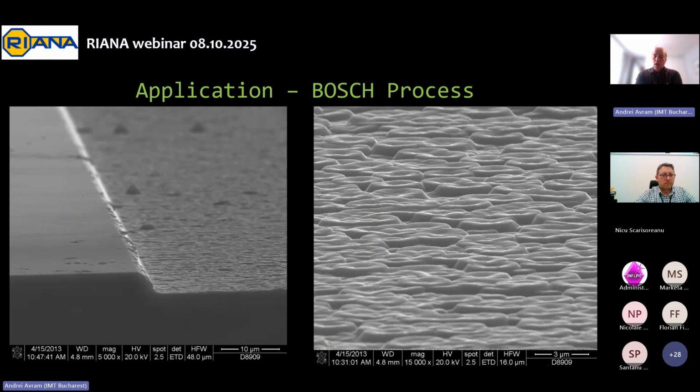We have used it in some projects with some colleagues of mine doing microfluidics, because silicon is very hydrophobic. You can actually use these types of structures or even these pyramidal shapes to make silicon hydrophilic if you want to do some microfluidics in silicon. So it's not a bad process, but if you can use it accordingly with your application, you can actually use even a defect.